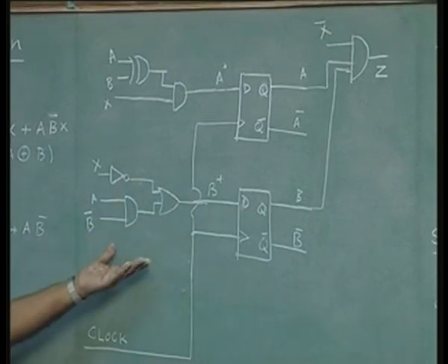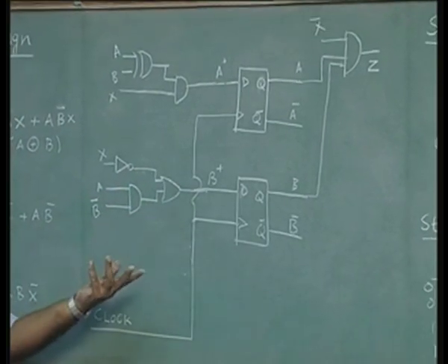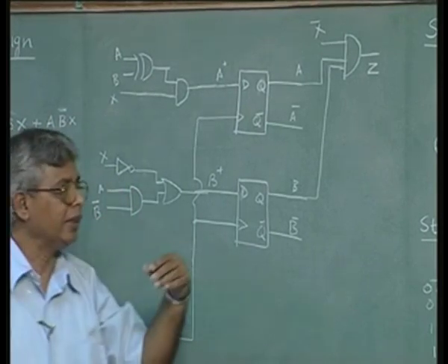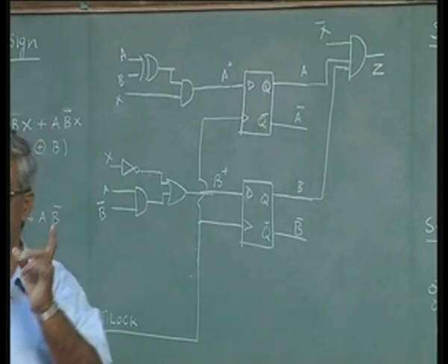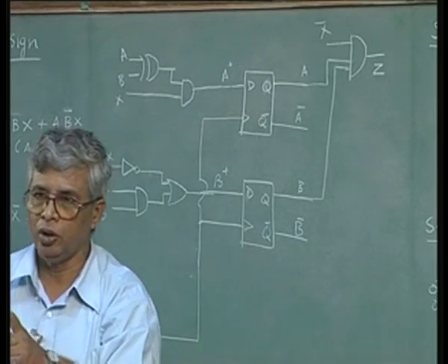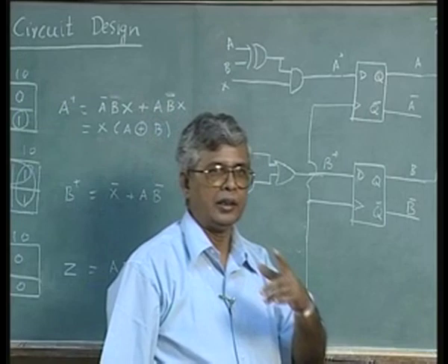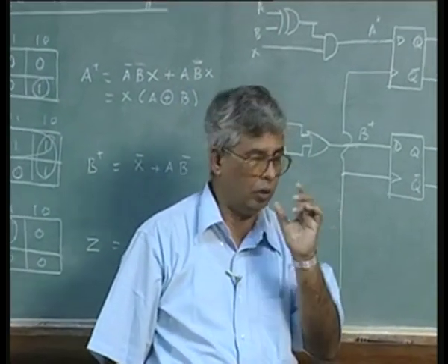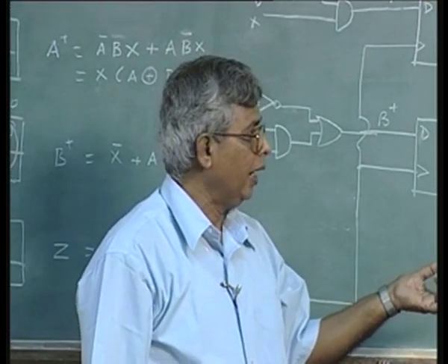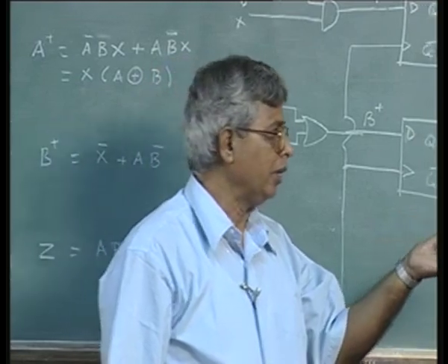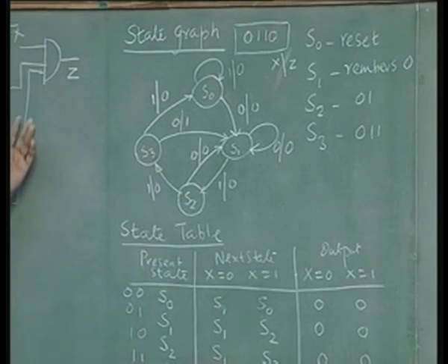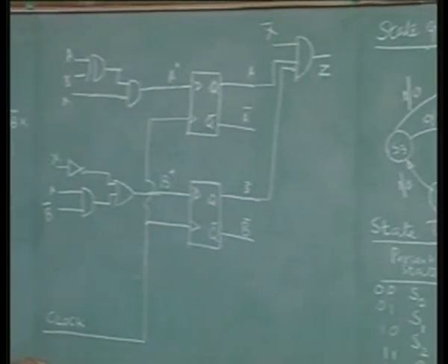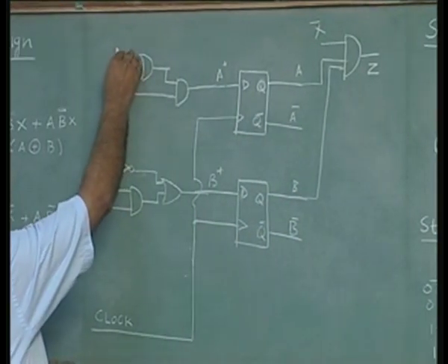So, now this is the sequential circuit implementation of the original pattern generator we started with. We wanted to detect a pattern occurring as 0 1 1 0, including overlapping patterns, and whenever the pattern is detected along with the last bit 0 we need to output a 1, and all that is gotten into this. So, this whole thing is now the Mealy circuit.